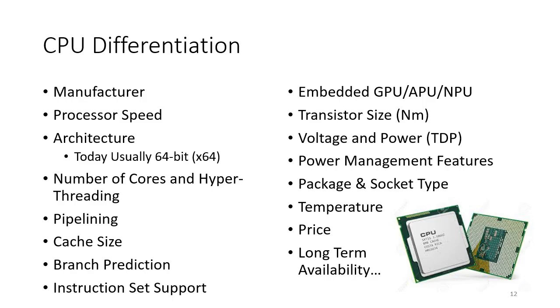Temperature rating, here's something else that you might need to be concerned with. Typical consumer grade equipment is rated at 0 to 40 degrees centigrade, maybe a bit higher, but when you're looking at industrial computers, you might want to go to 0 to 60. You might even want to go to even higher and lower temperatures. So a very rugged design might be minus 40 to plus 70. And if you're looking at some applications like automotive, the temperature goes higher still.